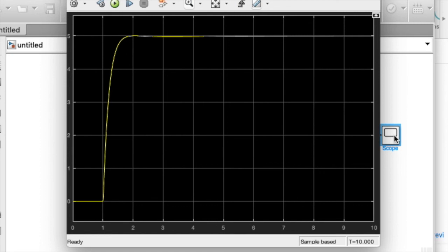Okay. But this will be the approach. You put a transfer function, you apply the comparisons between coefficients, you get your gains. That is your starting point. And then basically play with your transfer function, without even applying to the simulator, first you tune your gains using this Simulink approach. Just put your transfer function and see if your gains are good enough to at least give you a similar response in a separate Simulink file, and then go ahead and apply that to the simulator. So that will be the kind of design approach we will use.